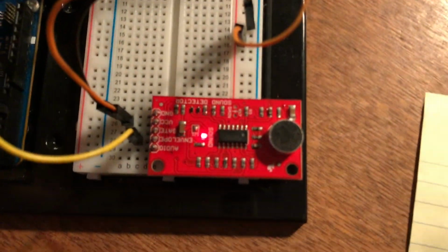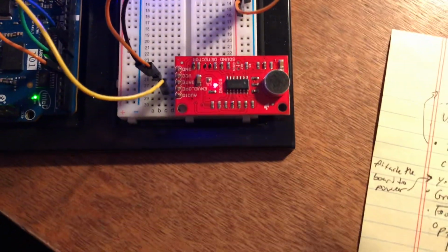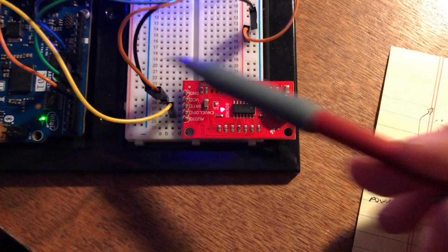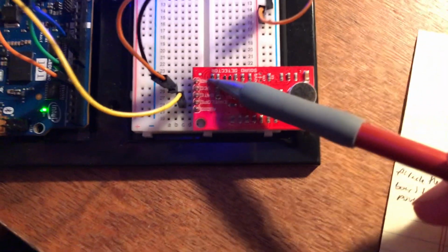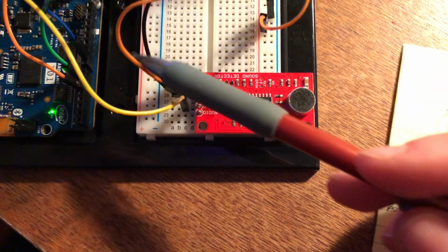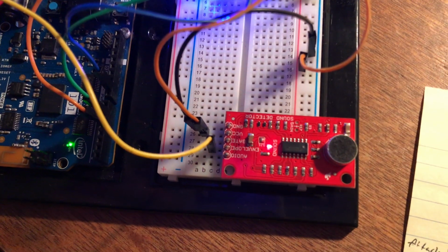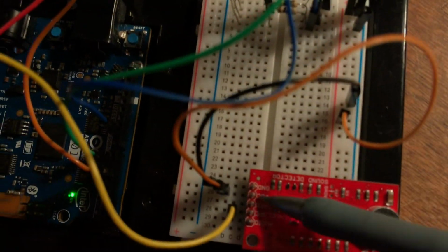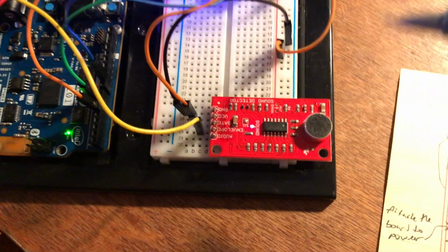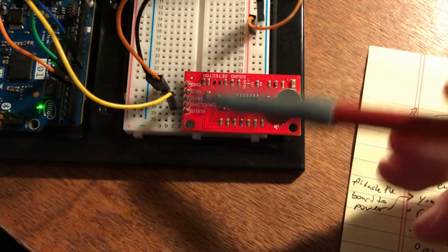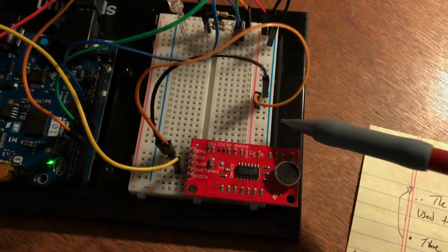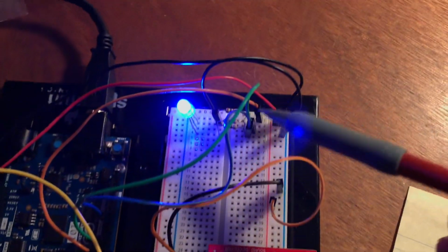So on the board, it is connected by 3 wires. It is grounded by the ground pin through this black wire to the negative column, which is grounded by this black wire here. And then the orange wire here connects to the VCC pin, which connects the board to power, which is 3.3 volts. So it connects to the positive column through the red wire to the 3.3 volts pin over here.